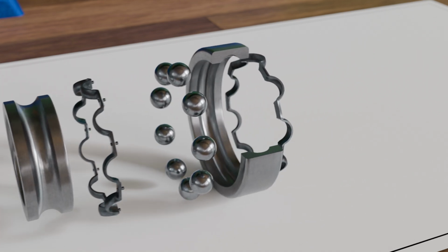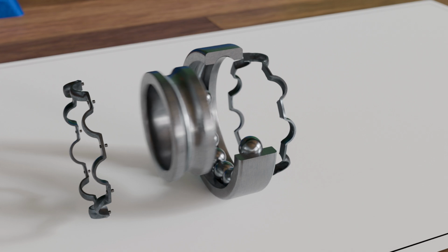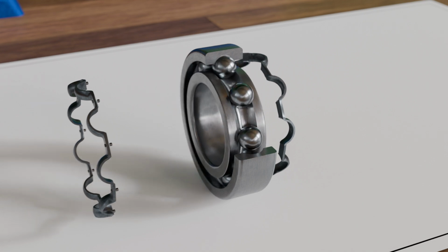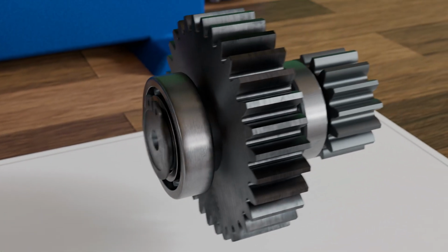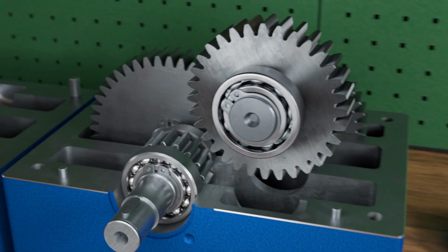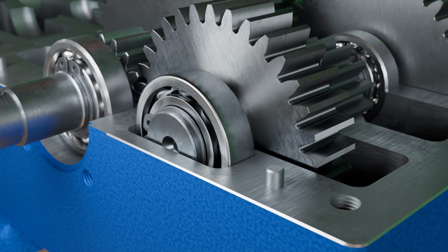The rolling elements move between an inner ring and an outer ring, also called inner and outer race. One of these rings is connected to the rotating component, the other to the stationary housing. In the illustrated gearbox shaft, the inner ring is connected to the shaft and the outer ring to the gearbox housing. On the inner surfaces of these rings are the raceways on which the rolling elements roll. To withstand high forces and wear, these raceways are hardened, usually to a Rockwell hardness of about 62 HRC. The bearing rings are typically made from wear-resistant chromium alloyed tool steels.